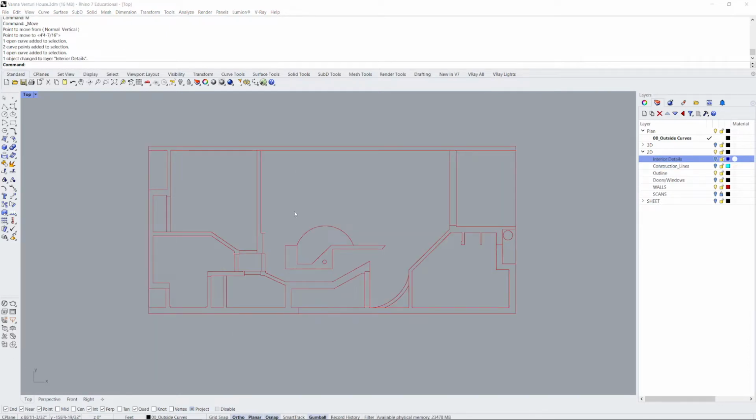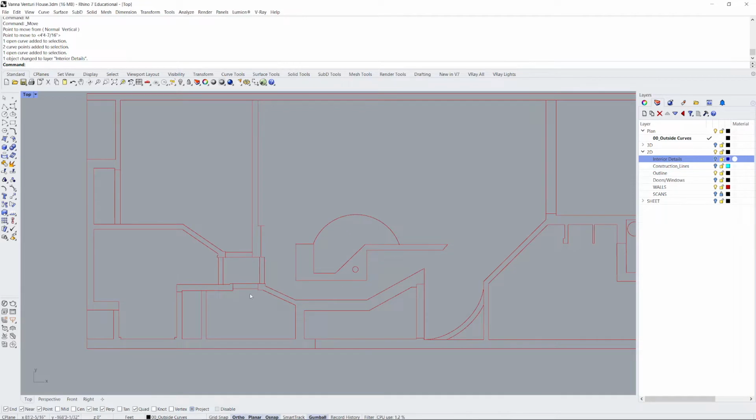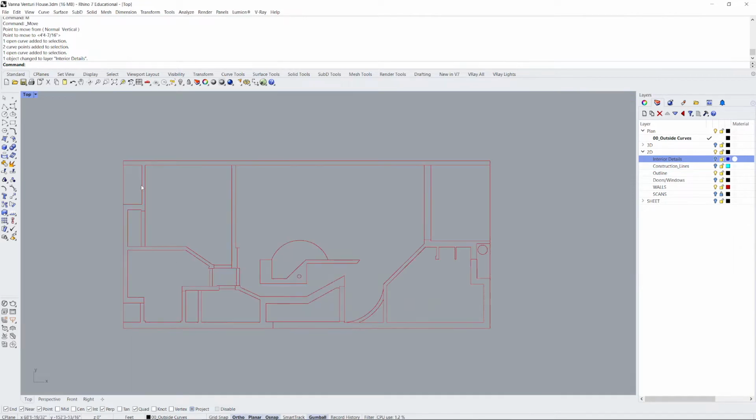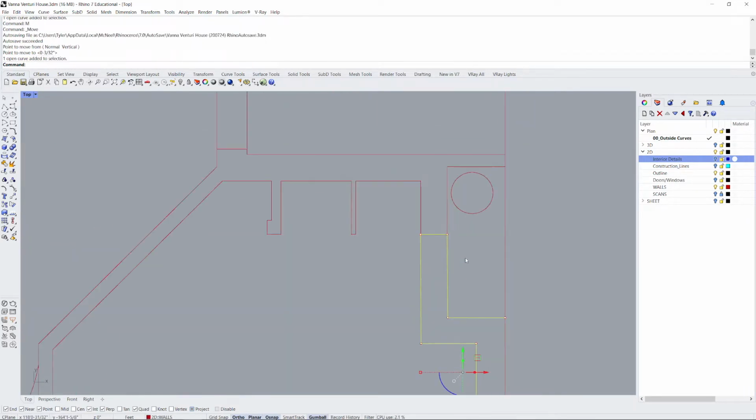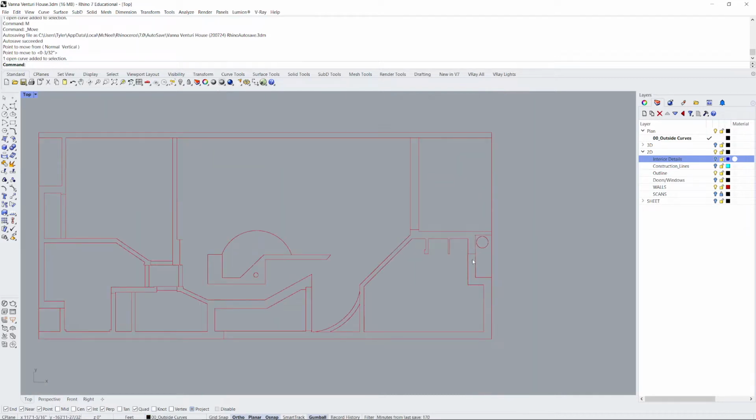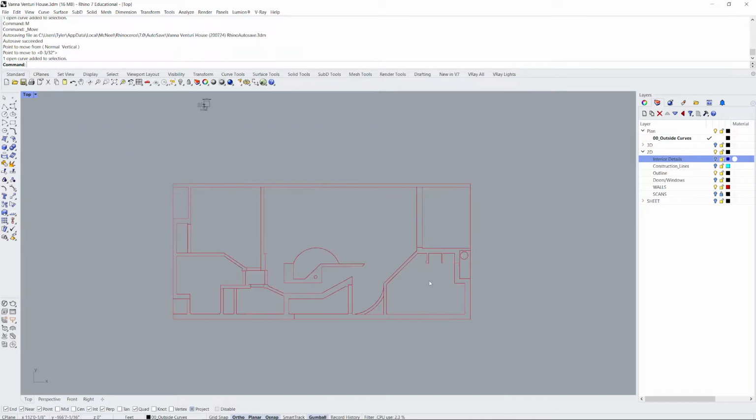Okay, so now that I've made sure that everything is a little cleaned up, I've got all of the walls where windows and doors would be. They just extend. That little door here would just move right across as a solid wall. So that way I can come back and I'll turn that line work on and I'll make any extrusions that would need to create doors as a separate operation.